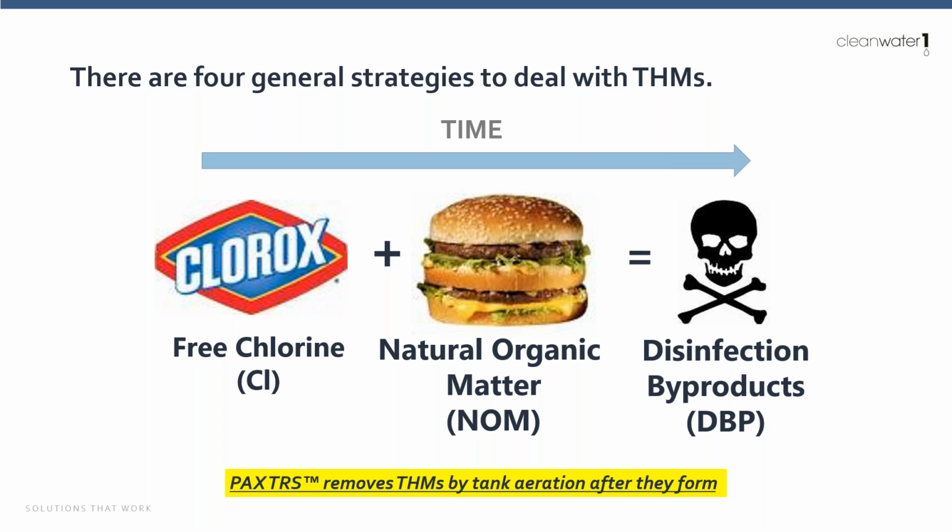So for example, I already talked about how out here in California, we do a lot of chloramination. So we've moved away from free chlorine to chloramines. Now, there are lots of reasons why that's not very popular and is really kind of an option of last resort. Dealing with chloramine chemistry is just a lot more complicated than dealing with free chlorine chemistry.